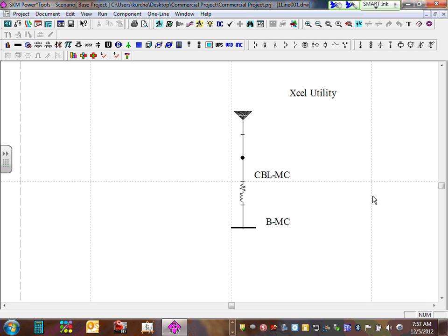Yeah. Cool. The naming and the acronyms that we use for the naming is so important because we did hospitals and you end up with close to 1,000, 2,000 cables in the whole hospital. So when you see a cable 76, where the heck is cable 76? But if you call it cable dash PL1, that's panel 1. I know that this is terminated in panel 1. So you give the cable a unique name, so when you're looking at them, you know where they're landing. Thumbs up, Chad. Cool. Okay.